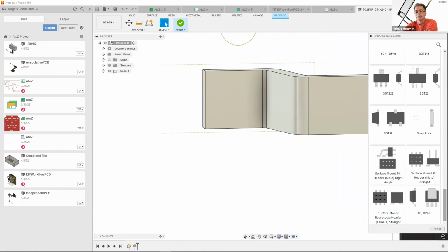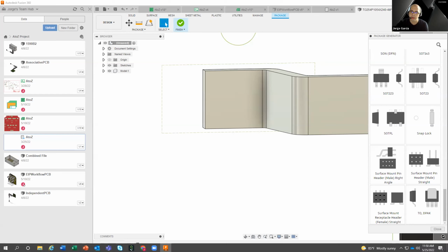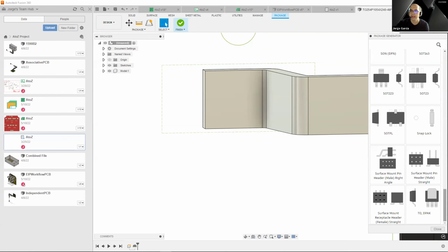If you're in a situation where this is going to be a space constrained design and it needs to have a lot of functionality, Wi-Fi, whatever, then maybe you favor going least so that it takes up the minimum amount of space that the IPC recommends. But that's the way that just from entering the physical dimensions, the pads are determined. It's basically a standard that the IPC has set up with those 3 levels of density.